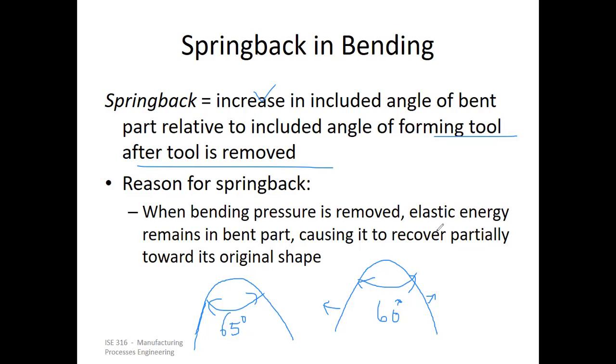If it was 60 earlier after executing the process, it will try to increase because of the elastic energy that is there. The elastic energy is not dissipated yet. Plastic energy has been given through plastic deformation, but the elastic energy is still there, and therefore that will cause it to return. That returning, or change of angle or dimensions after removal of load, is called springback. I hope that concept is clear.